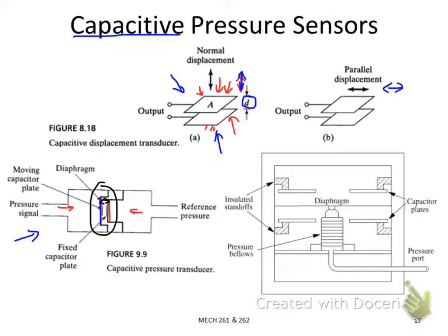And we also have another type here. This is your diaphragm membrane, and attached to the membrane, you have a pressure balloon below, which is connected to a pressure port. When you apply a pressure into this chamber, the chamber will move up because of the pressure, so finally the diaphragm will be deformed upward.